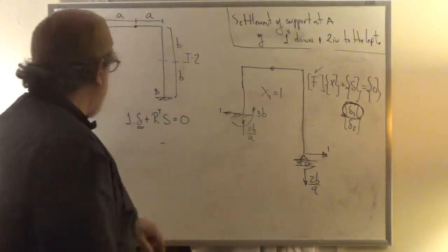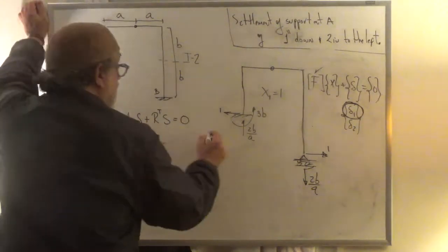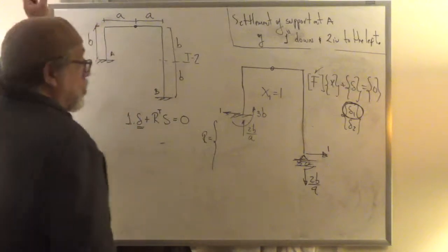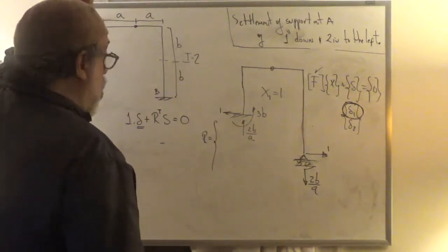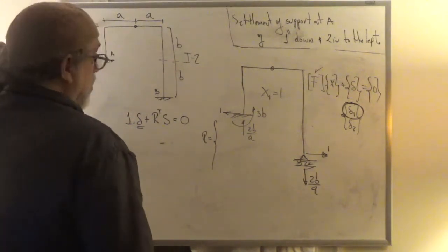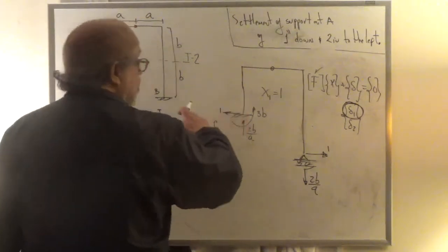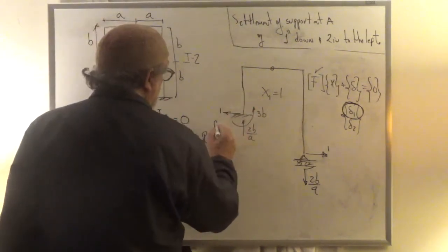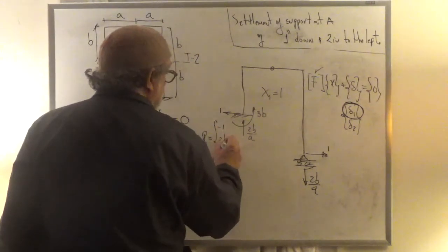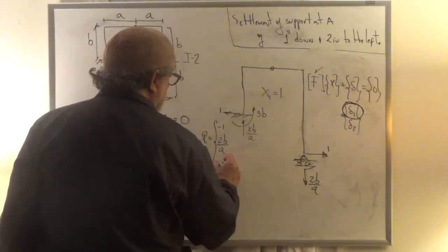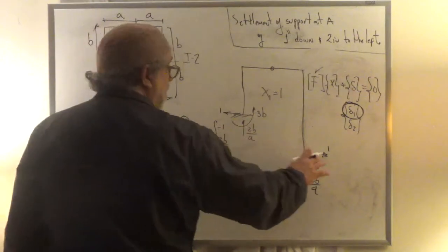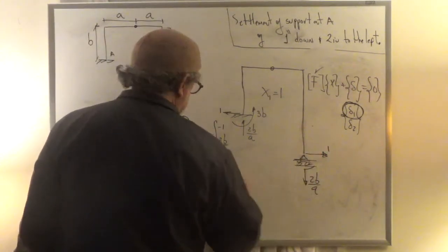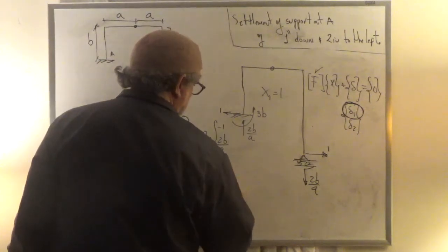We calculate the reactions. So what is our vector of reactions? It's a vector that lists the reactions due to the 1-kip load in any order you want, as long as you're consistent. So I will start on this side and use normal things like to the right, up, and clockwise. So it will have minus 1, 2b over a, minus 3b, and then over here, that's not a reaction, and this is minus 2b over a.